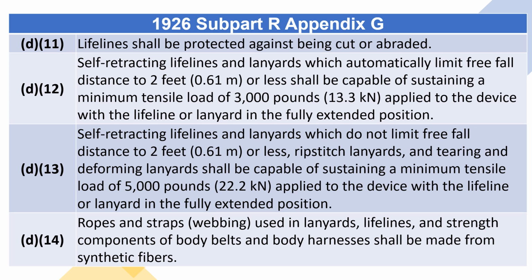D12. Self-retracting lifelines and lanyards which automatically limit free fall distance to 2 feet (0.61 meters) or less shall be capable of sustaining a minimum tensile load of 3,000 pounds (13.3 kN), applied to the device with the lifeline or lanyard in the fully extended position.